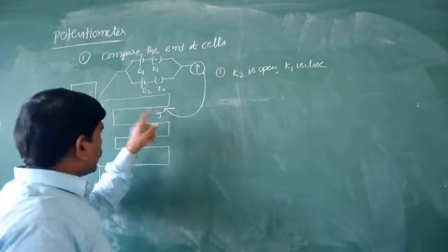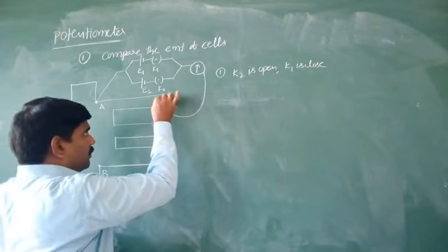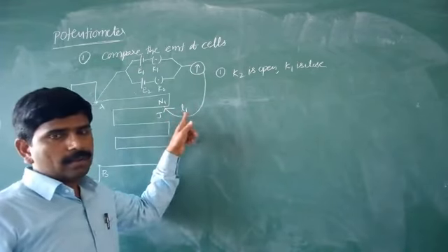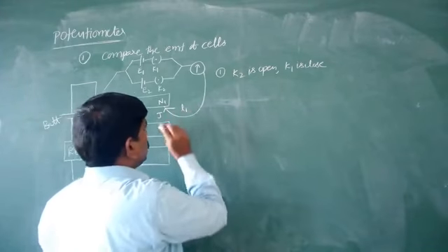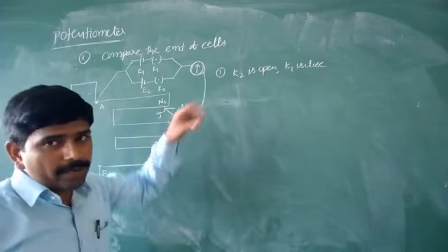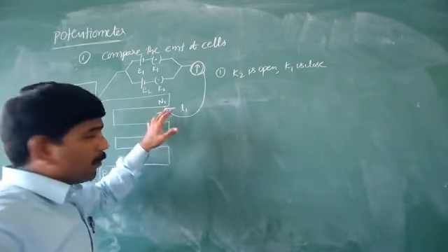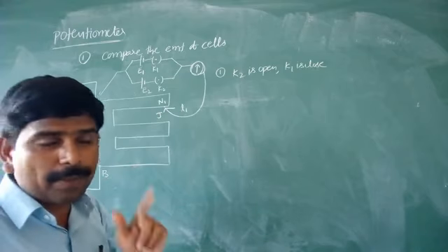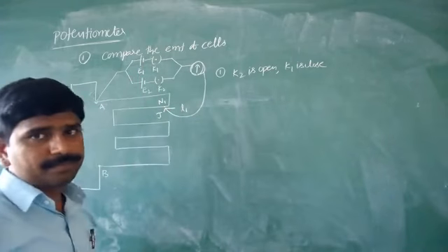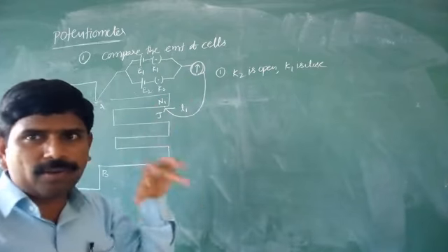Right now, if the jockey is moved from point A towards point B to a point N1 for the balancing length L1, in that situation this galvanometer shows zero deflection. It means the potential drop across the length of the potentiometer wire is equal to the EMF of the first cell.